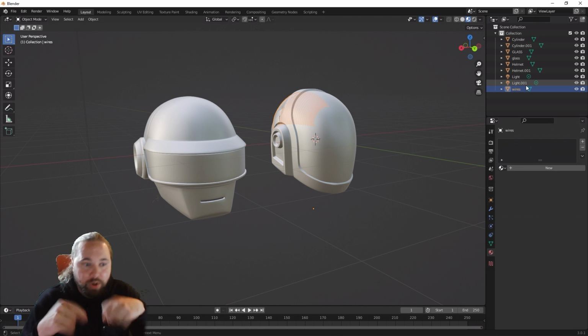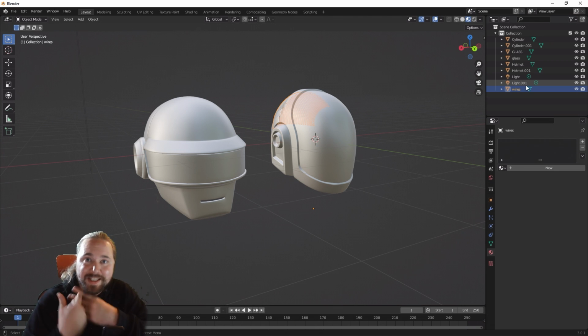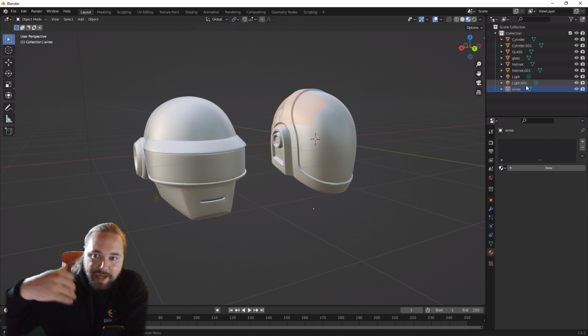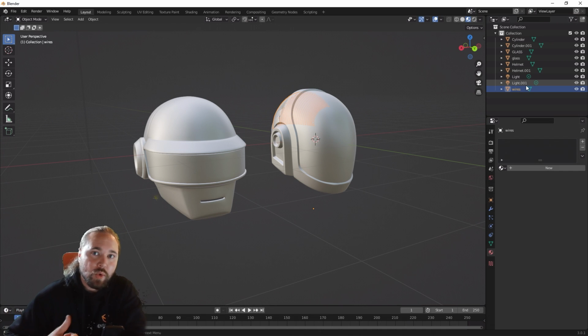However, I want to do something in Blender already, namely I want to assign certain materials. Because while we can edit given materials in the Enscape Custom Asset Editor, we cannot create new materials, and we cannot assign them to geometry.